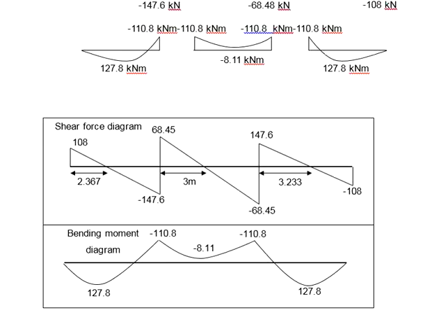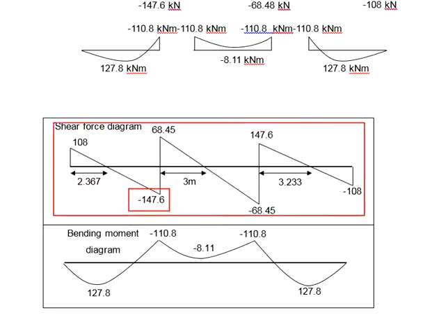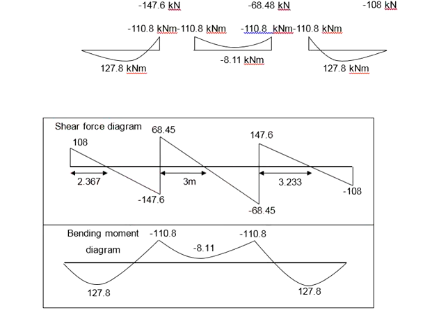Sometimes, if you choose to make it more simplified, you may adopt the largest moment and apply it to all. Also, you use the largest shear force and apply it to all. This can significantly reduce the steps that you need to deal with in the design of the beam, but it is going to consume more materials. The structural element will be more costly.